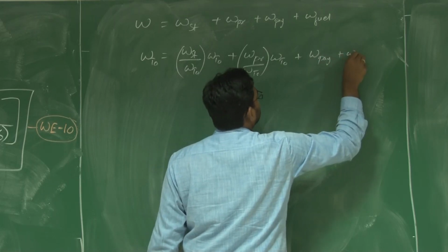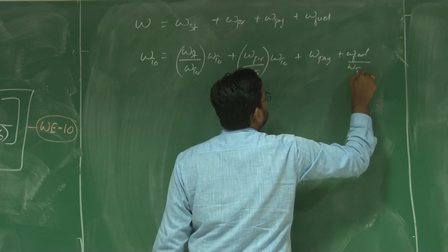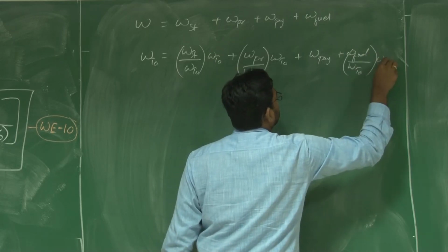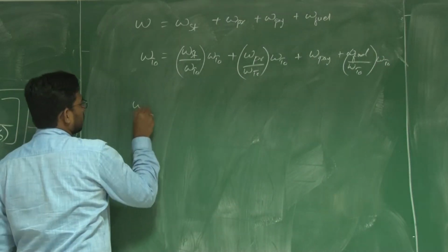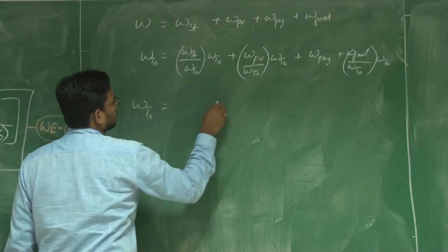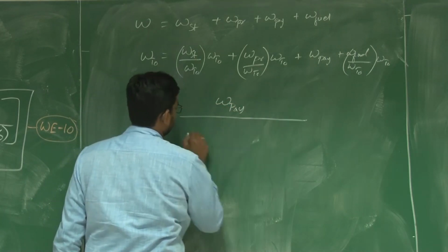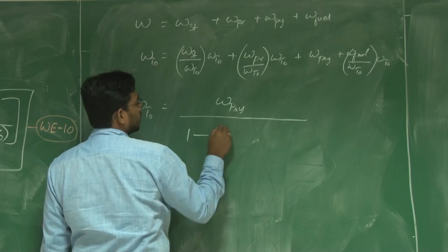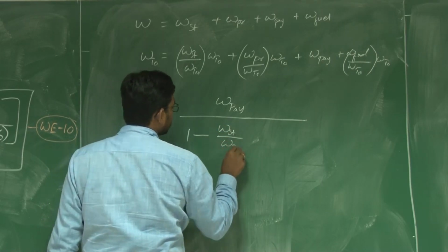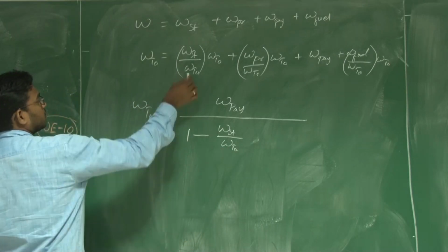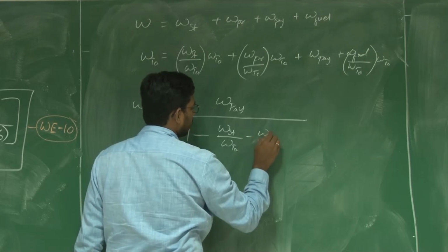plus payload plus fuel weight fraction. Right. So W takeoff is obtained by rearranging this equation, where in the denominator you have all the weight fractions,